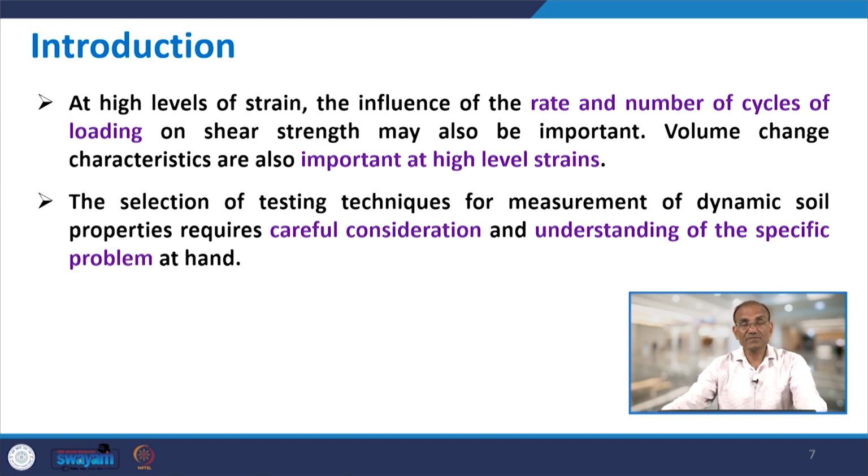Continuing with the difference in low strain and high strain: at high levels of strain, the influence of rate and number of cycles of loading on the shear strength may also be important, and that needs to be considered, particularly for high strain testing. For high strain testing, volume change characteristics also become important, and that also needs to be considered.